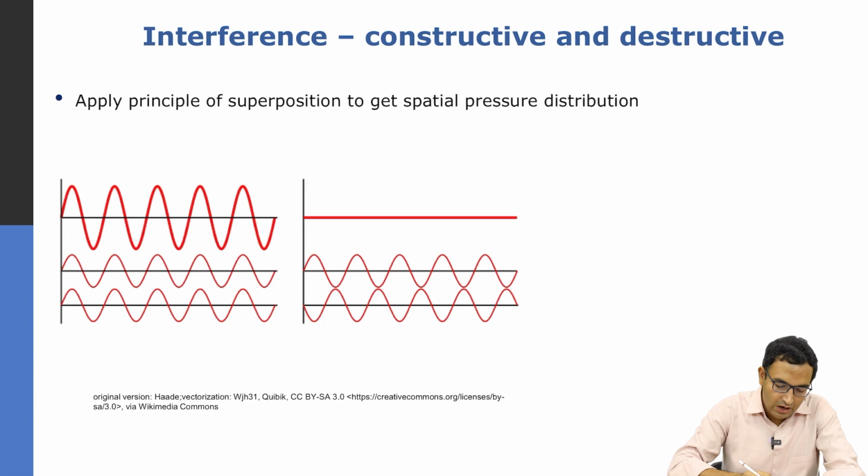Here is an image which shows the resultant signal. This is the resultant summation signal, and here are two sinusoidal waves that are in phase. As you can see, they reach maxima and minima together, and when summed they sum coherently. However, here these two signals are out of phase, so when you sum them up you get 0. So areas in which you have no beam energy, the signal sums up destructively, and the areas in which you have maximum beam energy, there is constructive interference largely.